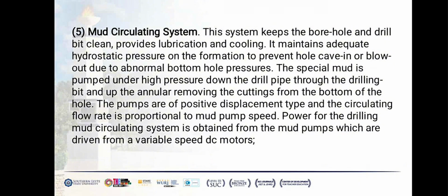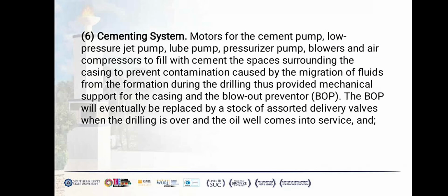The pumps are of positive displacement type. The circulating flow rate is proportional to mud pump speed. Power for the drilling mud circulating system is obtained from the mud pumps, which are driven from variable speed DC motors. Number 6. Cementing system.